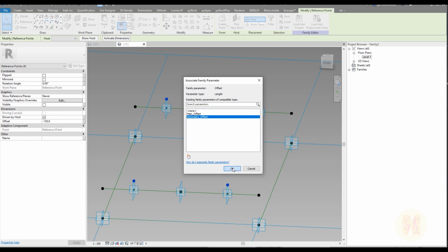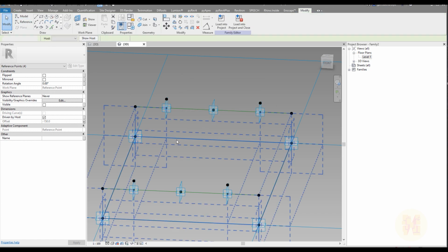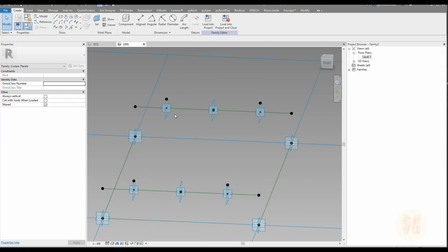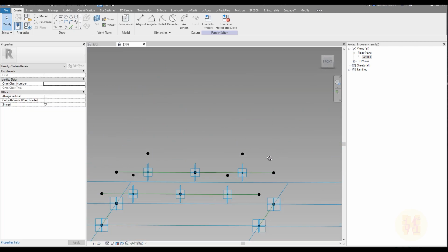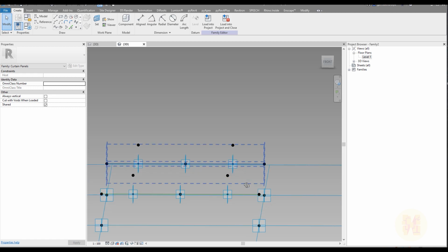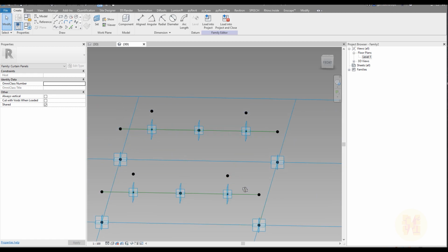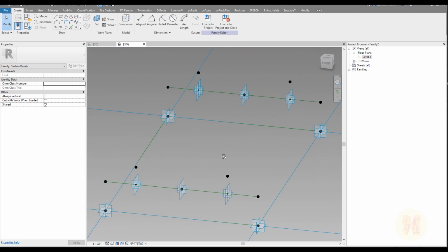So we did it. The secondary offset we have, but the distance I want to use, let's change from minus 150 mm to minus 300 mm. So now it's much better. Maybe you can actually offset more, but it's already by your taste. If you want to do it, it's not a big problem for us.